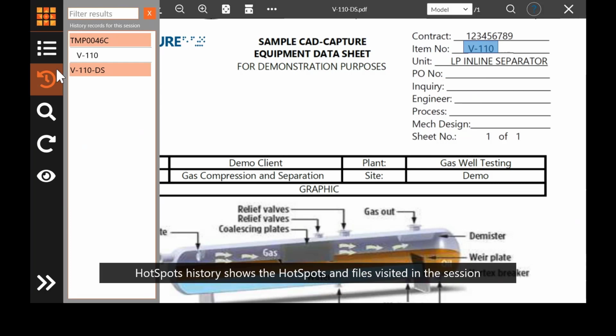So whether it be a task being carried out and paused at the end of the day or over lunch, or a maintenance task which is carried out periodically. So the benefit there is the next person, and it doesn't have to be the person who carried out the original overhaul, can access that information and see the drawings, tags and documents that were referenced the last time that task was carried out. So we'll go back to the original P&ID.